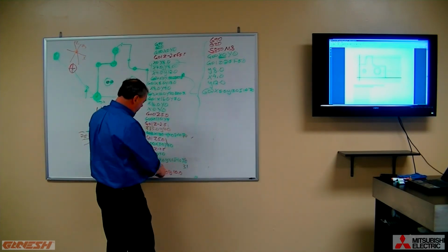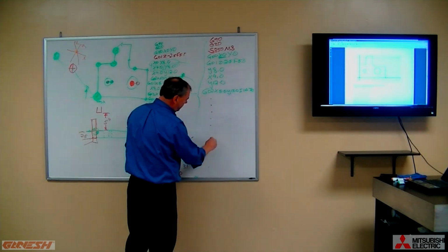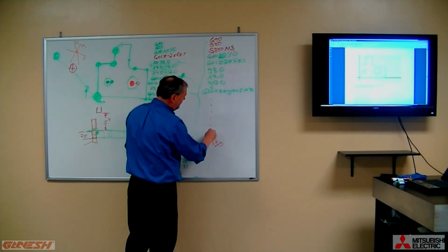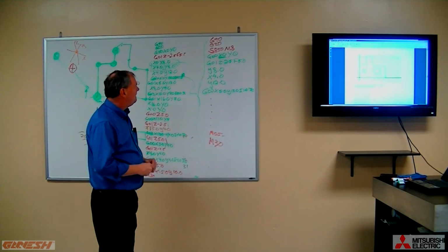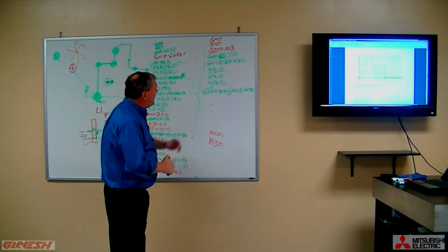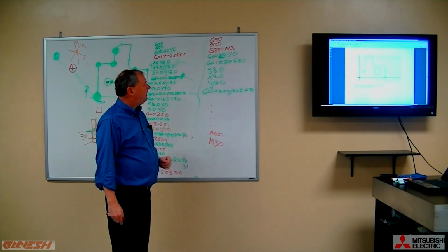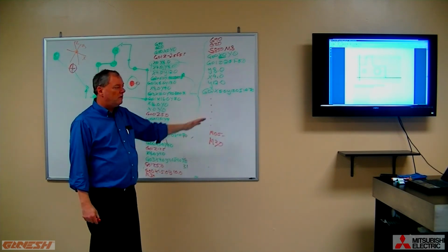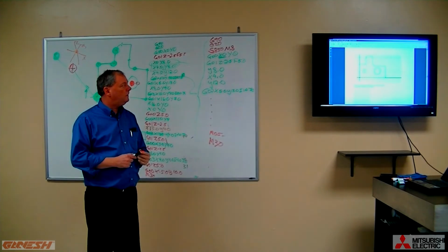And when we're all done machining, just before our M30, we're probably going to insert a code that says M05, which means turn the spindle off. So now, with these corrections, we basically have plenty of program code to produce this part if we wanted to.